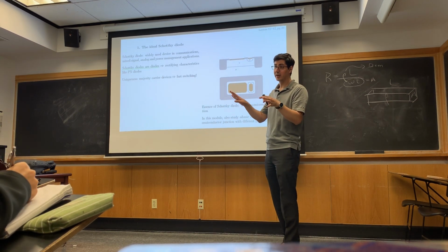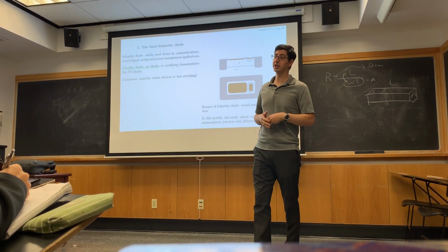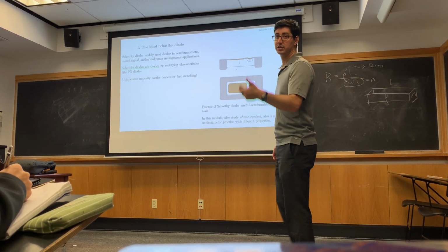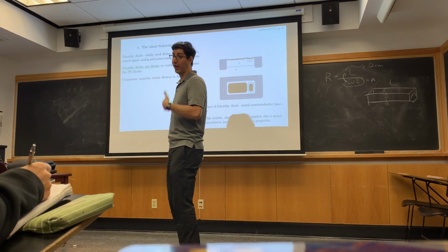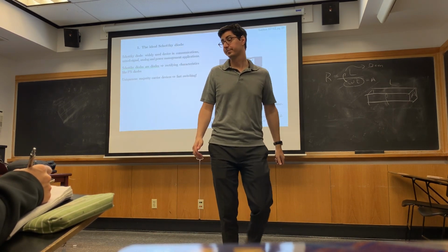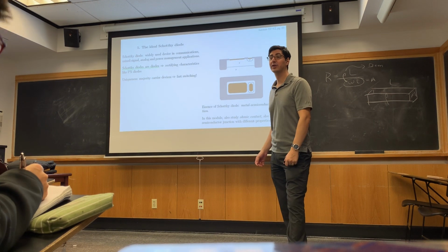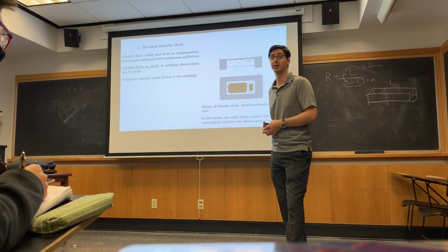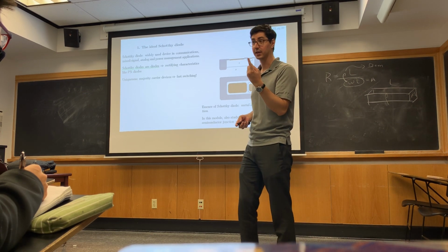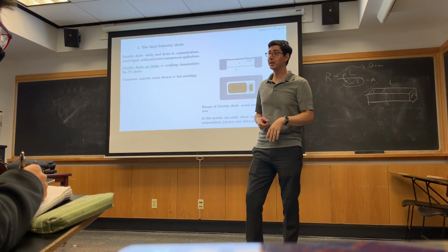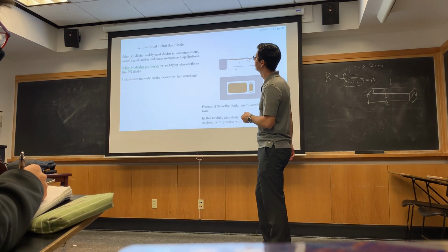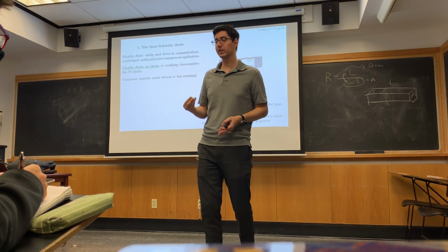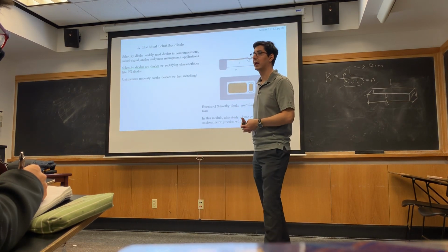Now, all the behavior of the device isn't going to be different. Its switching characteristics are going to be different. Okay? And so Schottky diodes are really fast. PN diodes are not super fast. And remember, fast, we're talking about picoseconds, under nanoseconds, right? In the world of electronics, a gigahertz is already kind of slow now, right? A gigahertz is 1 nanosecond, right? If you want to have a really fast device, RF, in analog, you know, it needs to be much, much faster. Its intrinsic speed needs to be much, much faster than what you're using it at.